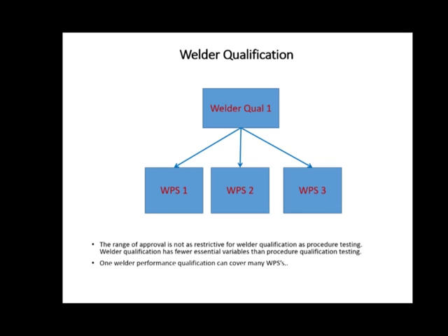So when I went from WPS 1 to WPS 2 and I went from carbon steel to stainless steel, that's a change. That's a new WPS. And the same from going from WPS number 1 to WPS number 3. I changed my shielding gas. I've got to change everything. Well, the welder, he's just got to qualify on F6. So F6 is filler metal, and it's the form that the filler metal comes in. So whether it's carbon steel or stainless steel, they all fit under the F6 category.